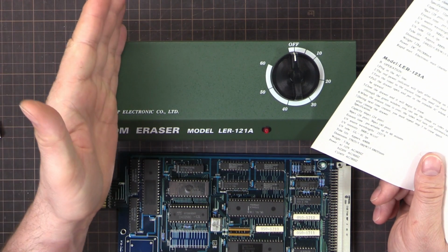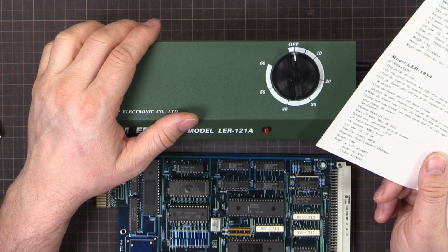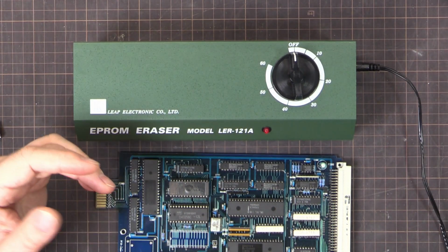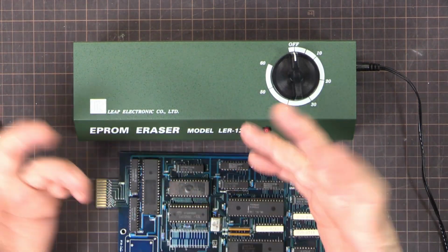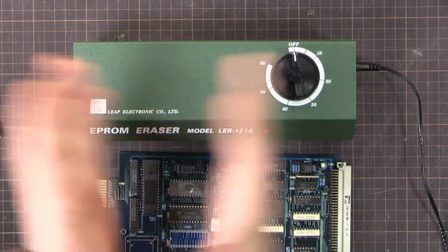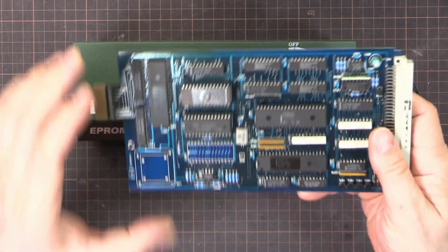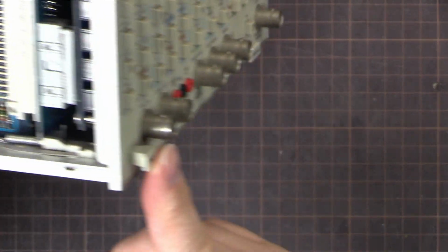So that means we've got to expose it for 2.5 times longer. I gave it 45 minutes because that felt right. It's not too long, not too short. Then once it was done, I put it into the programmer, and I can actually test. A lot of these programmers you can test to see if it's a blank chip, and it came up blank. So I programmed it, and it was fine. So we're done.